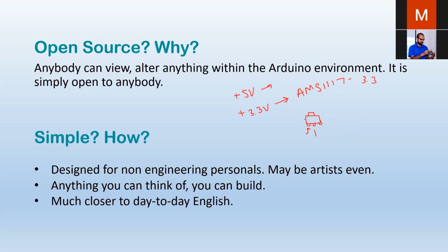When you input like 9 to 12 volts, they output certain constant voltages. These are actually called LDOs, the linear low dropout regulators, right? So these are not that efficient, but the output is really stable and really smooth. That is why we use them to power MCUs. Anyway,